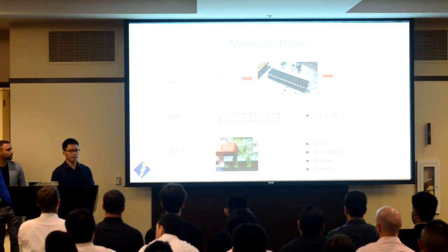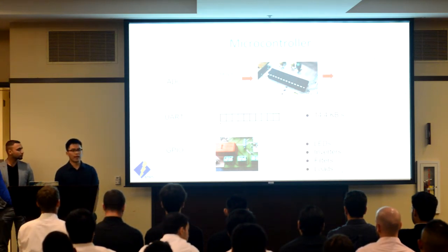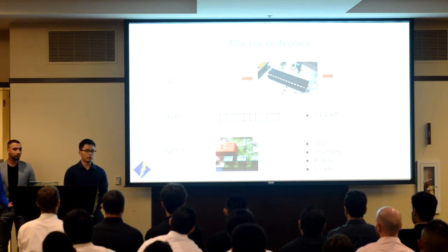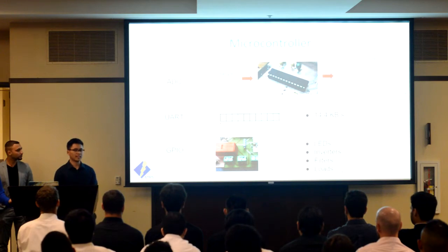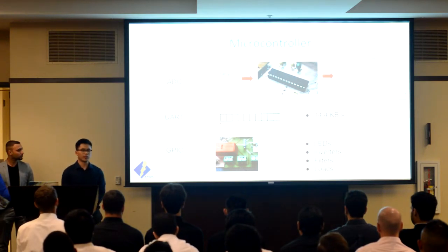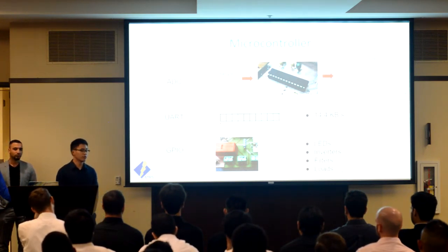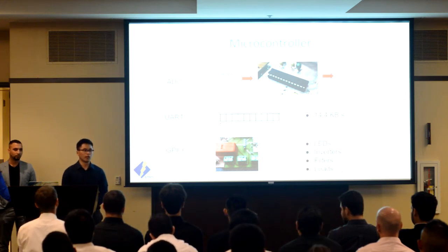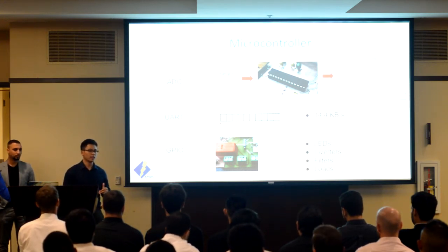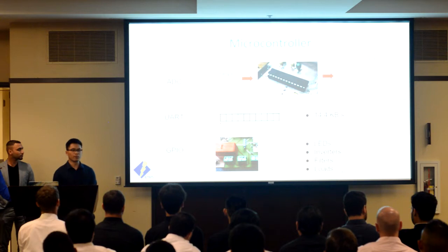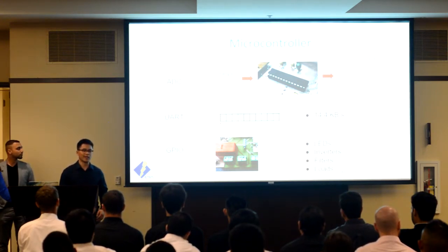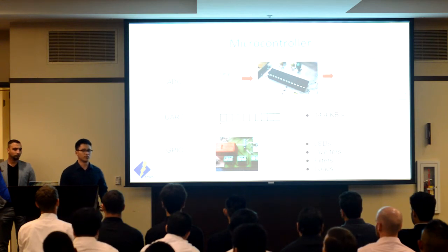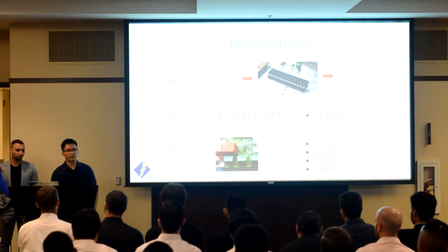And the last peripheral that I'm going to talk about is the GPIO peripheral, which allows our microcontroller to set the relays and essentially allow the user to select between components such as our inverters, our loads, and our filters, while simultaneously also setting our LED connected to these respective components, which are on our faceplates, so it allows the user to easily recognize which component is in use. I'm going to pass it on to Daniel to cover the communication flow.